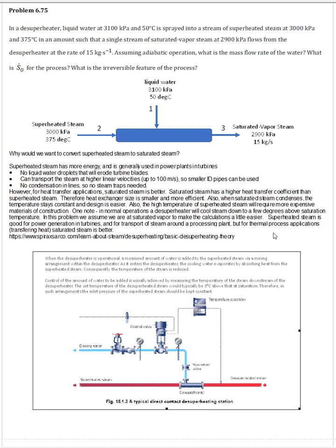But once you reach the part of the plant where you are doing heat exchange, you would then want to desuperheat that steam, cool it down, and convert it to what's known as saturated steam for those heat transfer applications.